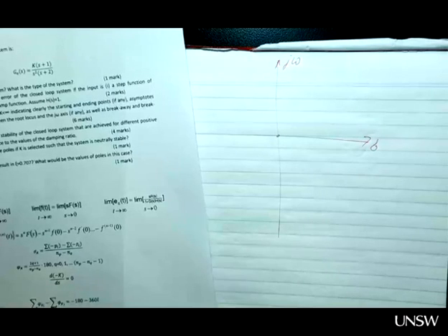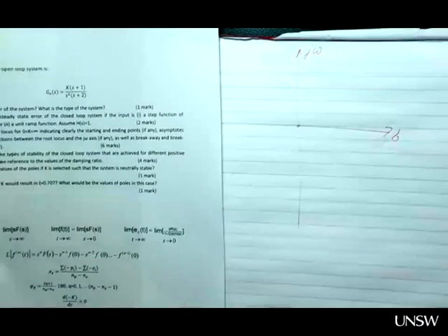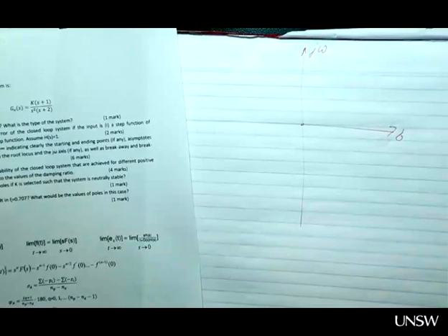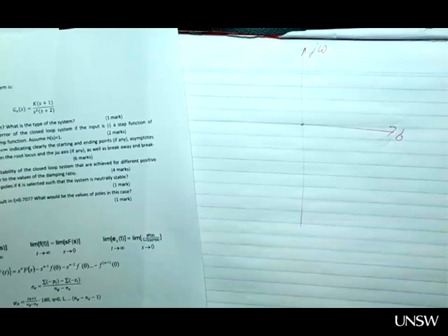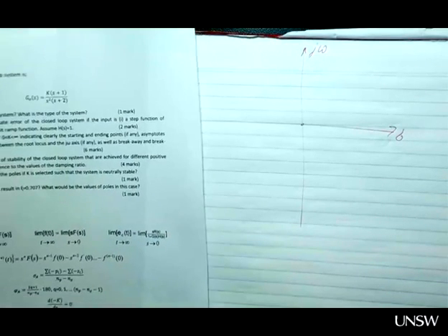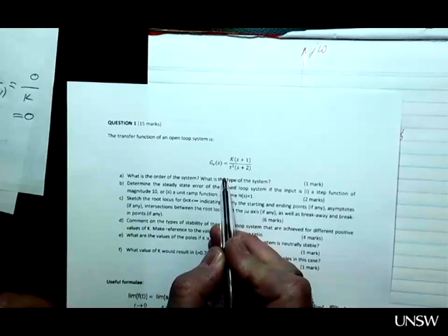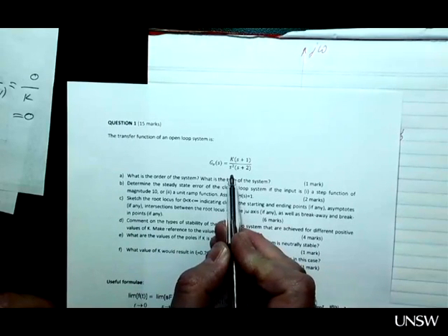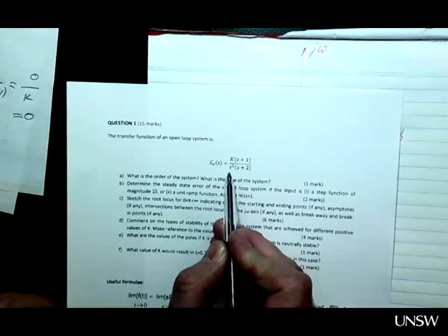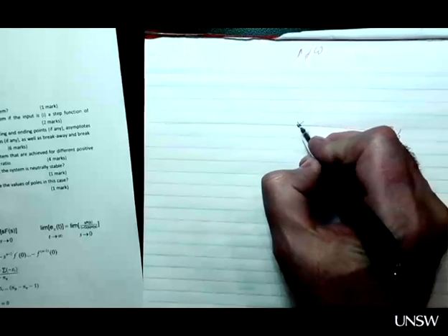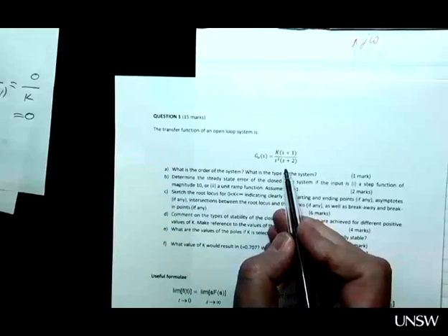First of all, let's determine those points on the root locus where k equals 0. Those points are the same as the poles of the open loop transfer function. So find these poles. There are 3 of them. 2 of them are at 0, so you have 2 poles coinciding here. And the third pole is at -2. So you have 1 pole here at -2.